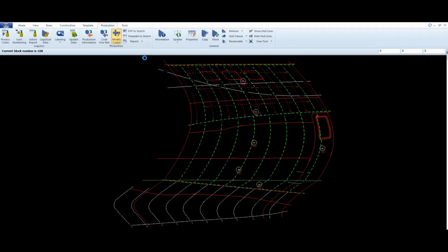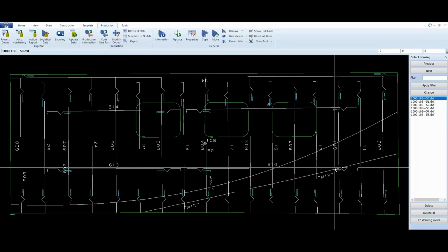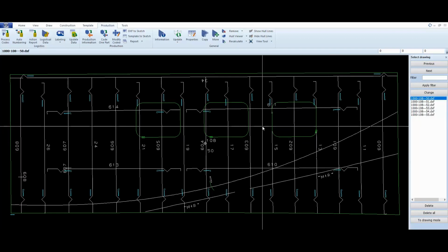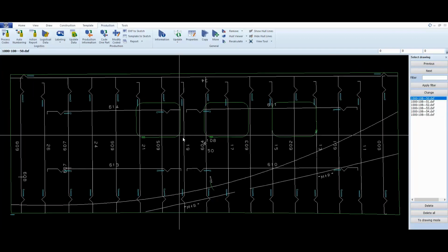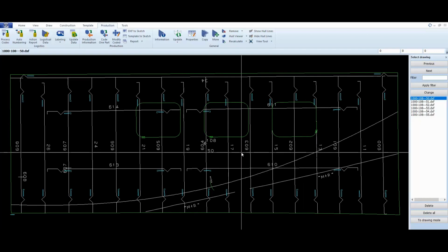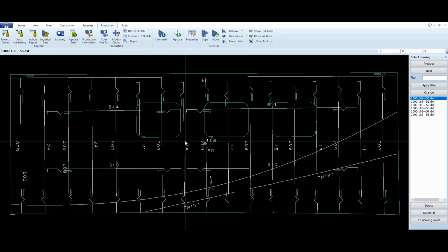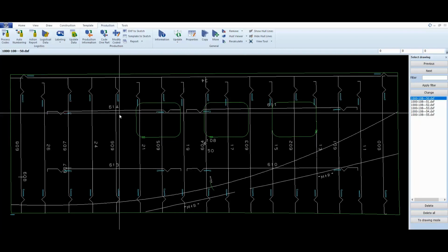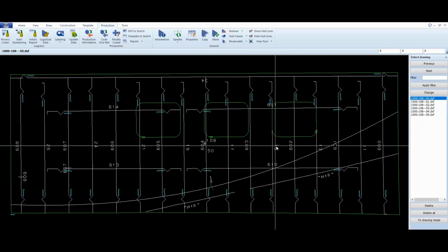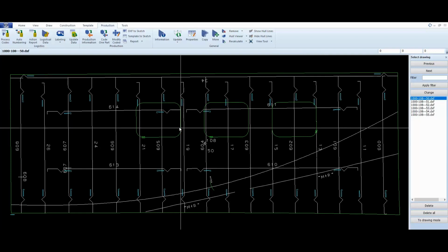Okay, production modify coded, and here we have again the list of DXF files for our shell plates. The last item I wanted to show you, to explain actually, is these green lines here. These green lines are actually the hull lines we have created before, the sequence of hull lines we have created by using the apply button. And why are they green? That is because their production property is defined as cut. So the system will use the cut properties when coding these hull lines.